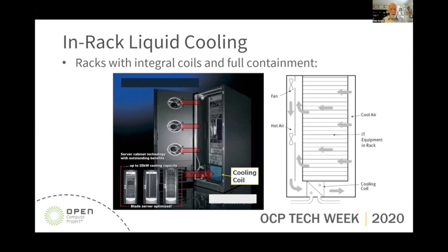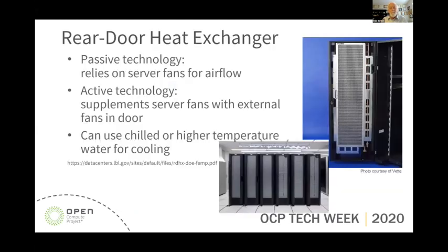We're going to start with in-rack liquid cooling. Typically, they're equipped with integral coils and full containment. This often requires some pretty high pressure drop through the cooling coils because the cooling coils need to be compact, but it's a good solution for edge applications.